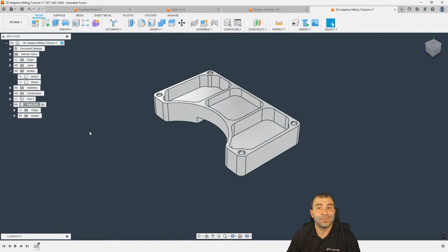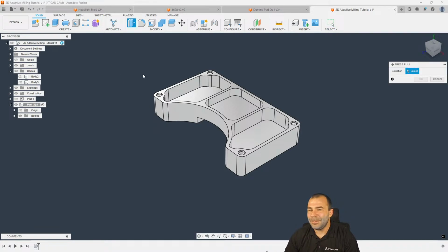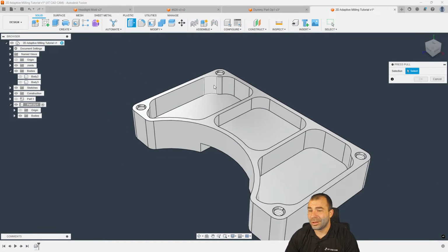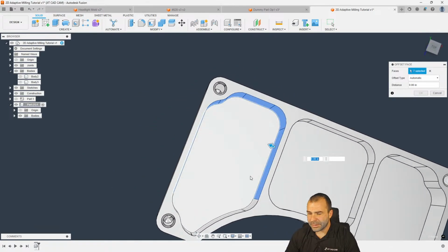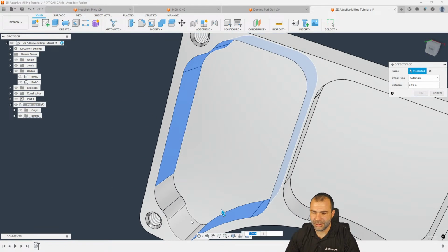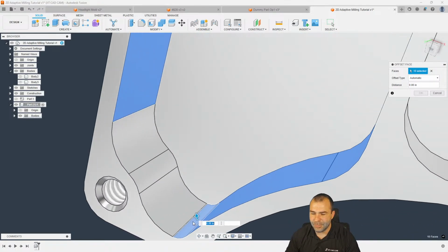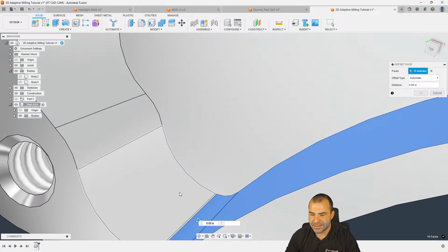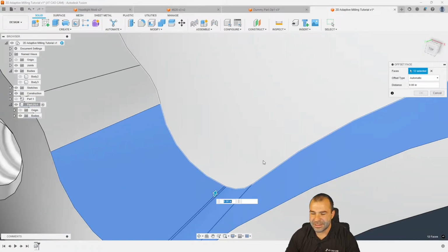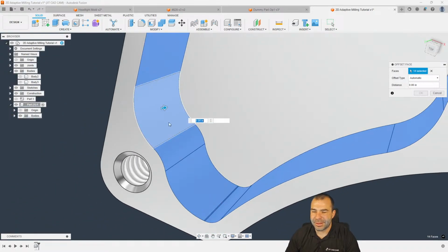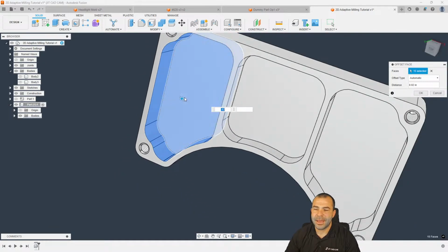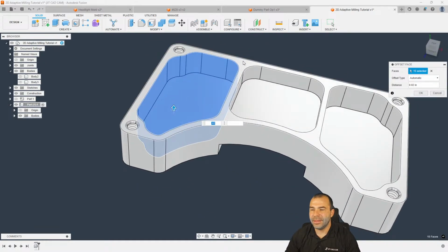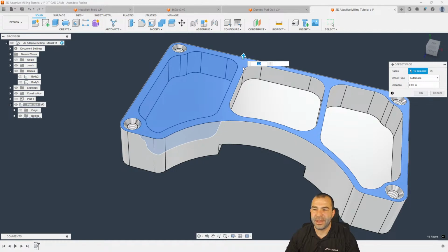Hopefully your engineers have provided you with the casting and the machined part. But on a simple part like this, using press pull goes a long way, right? So let's say, for example, inside this pocket, there's going to be 20 thou worth of material everywhere. So what you see me doing is going through and picking all these faces. Now I've got to get in here close enough to get this face. I used to have a space mouse, but the thing died on me. And I'm going to give 20 thou material there. I'm actually going to add 20 to the floor. And let's just say, for example, we're going to add 20 up top too, right?